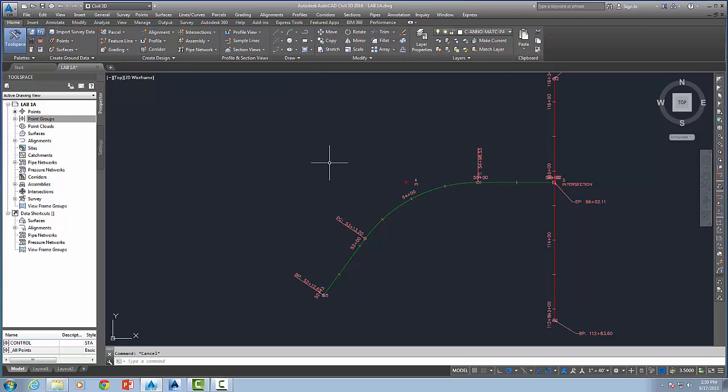Okay, so we're now going to create some offsets, and we're going to go back to that first sheet that we had. You'll notice the first sheet shows our geometry, and the second sheet shows me widths, and we might envision this being pavement width lanes. So I've got like a 30-foot width coming in off of the Township 35 here, and the 247 is at a 40-foot pavement width. So what I'm going to do is offset this.